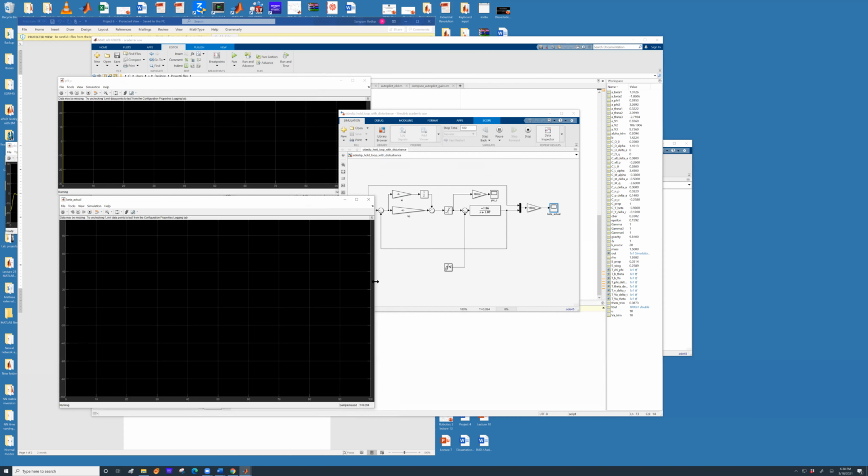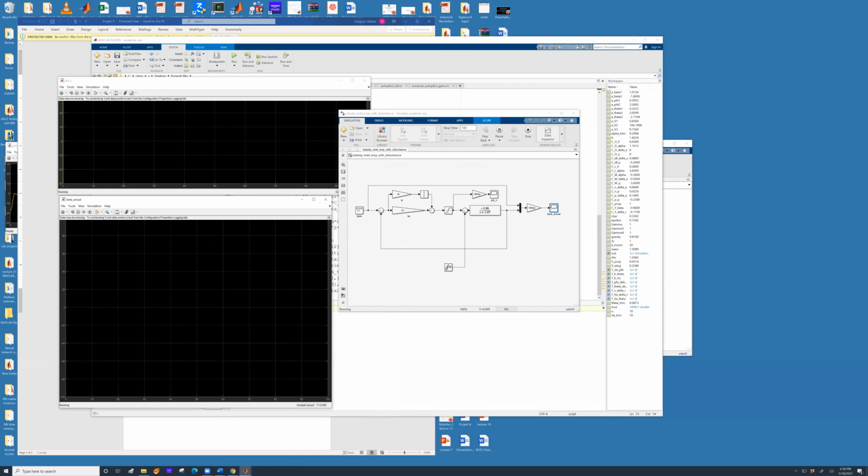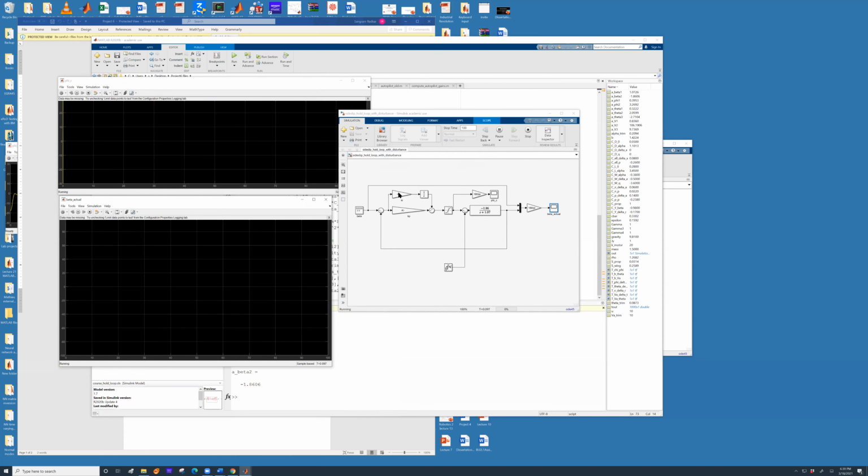So as you can see here, this tells me that to reject that disturbance, just using Kp and Ki, the amount of control effort that is needed is super duper high. So what I'm going to do is, just for demonstration purposes, remove the saturation block and attach this over here to see if our disturbance rejection scheme is working or not.